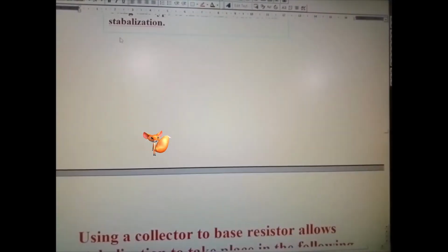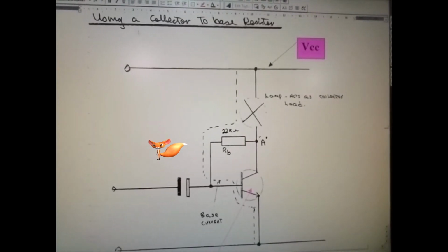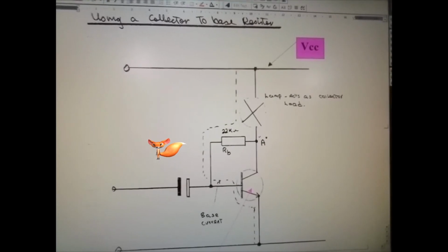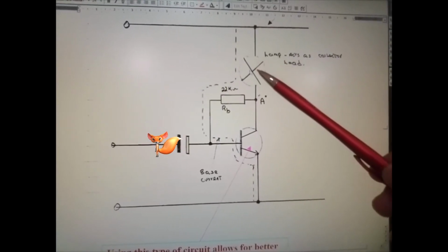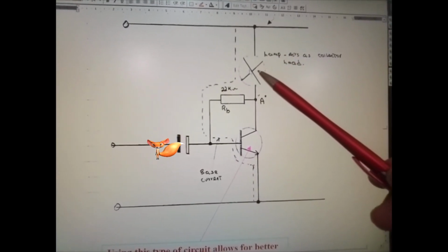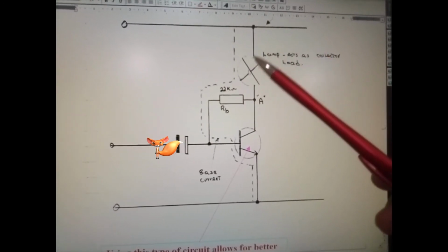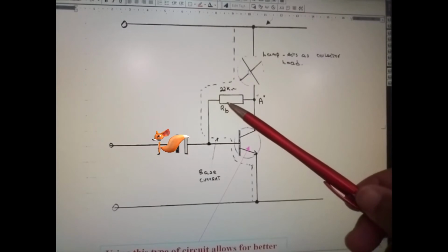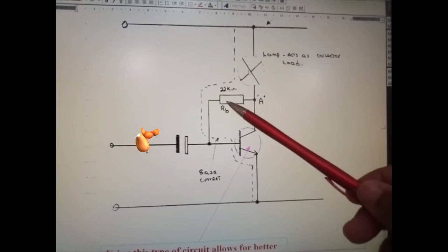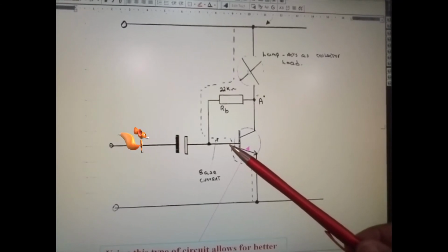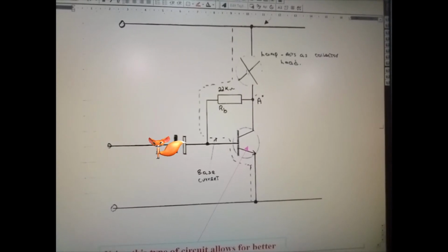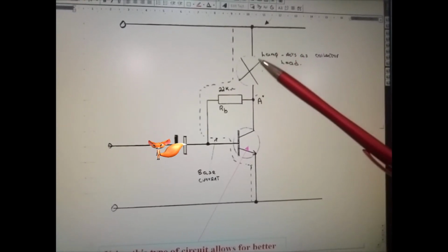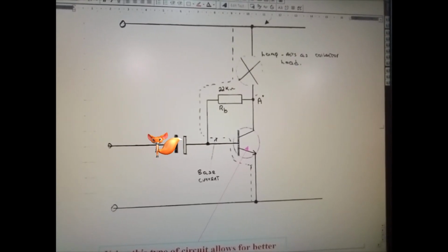Now, when you actually put these circuits on the breadboard, you can play around with them, and you can change the value of the resistors to see what happens. You can put a resistor in place of the lamp, or you might want to put an LED in place of the lamp and see what effect that would have. And you can change the value of this resistor here to see what changes. By changing that value, what effect would it have on this base current, and you can see how it causes your lamp to be dimmer or even brighter in some cases, again depending on the load.